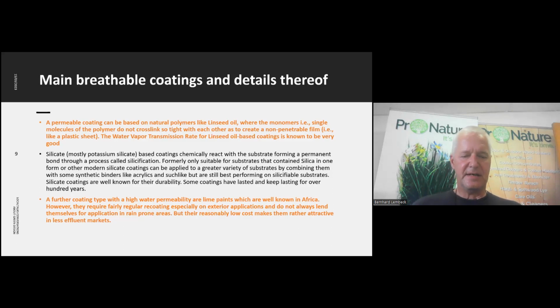But on the other hand, it also allows to protect the walls from the ingress of water. So obviously you don't want to have an earth-based paint or coat wall plastered with the formulation that you presented to be rained on for any length of time, and then the whole building to collapse, or at least the plaster to fall off.